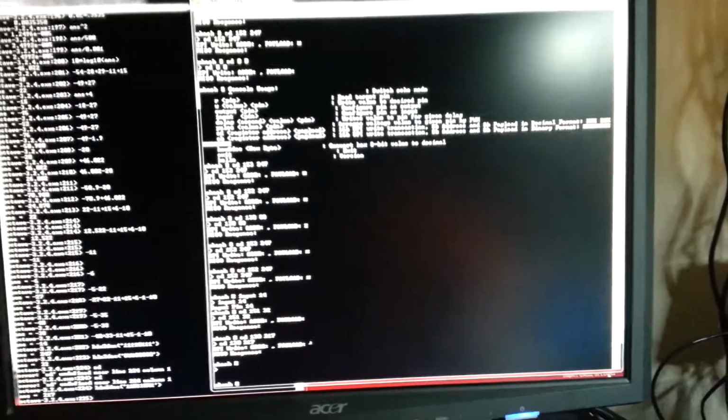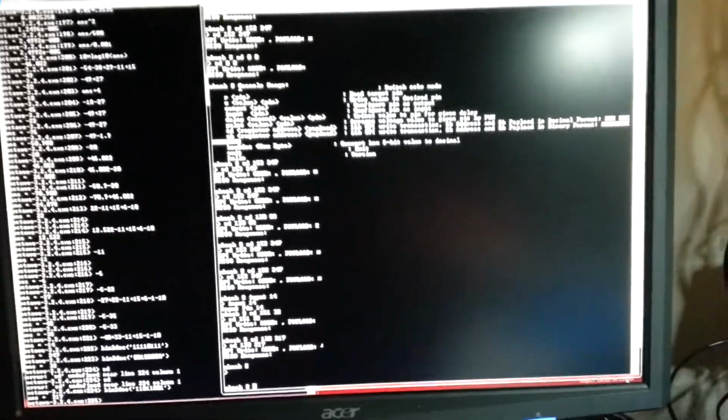The importance of a shell-based scripting system is that you can peek and poke individual registers on the target and configure your device under development instead of actually writing a whole software routine, compiling it, experimenting, and then retrying that. In this particular case, you can just write individual registers and determine if that write resulted in a performance that you expected.